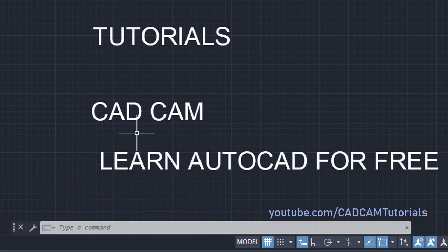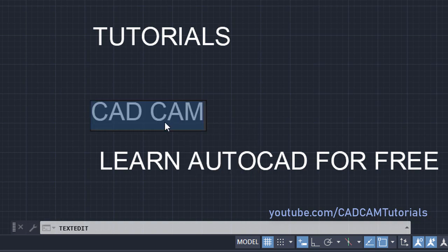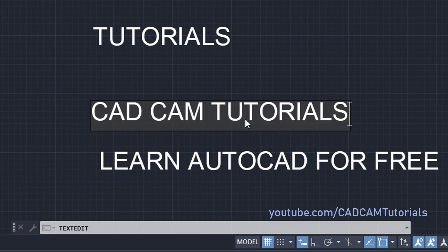Then if you want to make any changes to already written text, you will have to take your cursor over that text and double click. It will activate this text edit command. You can also type text edit and select the object. By clicking, you can type what you want to edit. Suppose I want to write here tutorials.